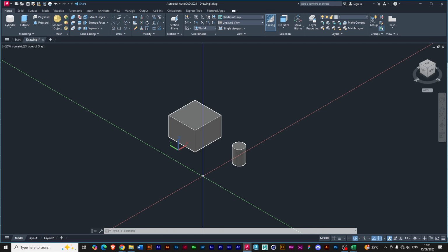Once you lie the paper flat down, Y, which was pointing up, is now pointing forward, no more up. So the z-axis that was pointing to you now turns upwards. That is why the coordinate system is like this. But the user coordinate system here in AutoCAD is dynamic, as in it's adaptive, meaning I can switch it.